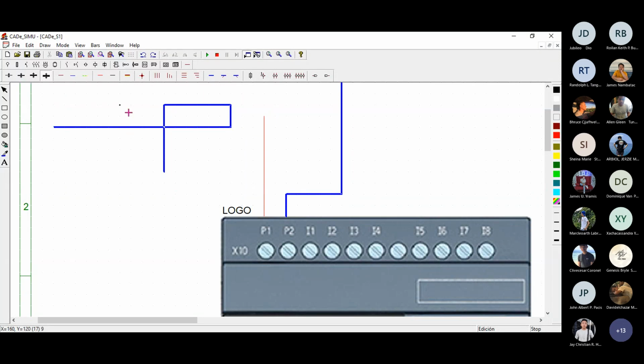So now for two wires, for example, you want to connect another wire from here, or you want to tap another wire. So you want to connect it here, so the software will automatically, for example, you connect a wire here like that. If you look, there is a presence of a dot. Which means that this wire and this wire are connected. And if you look at this one, this wire going up, going to the left, and going downwards, please take note that these two points here, even though they cross, are not connected.